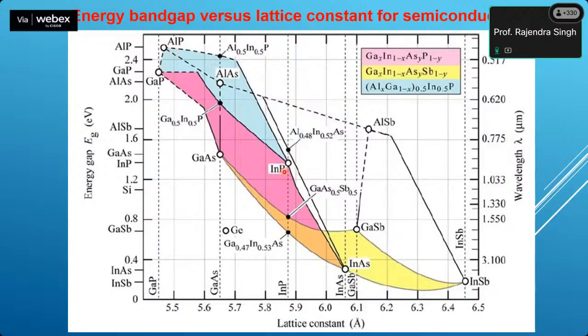But with sophisticated band gap engineering and material synthesis techniques, we can now tune the band gap. How is the tuning achieved? Tuning is achieved through alloying, or mixing. We have techniques, which I am going to talk about. We can mix gallium phosphide and indium phosphide in any proportion, from 0 mole fraction to 100%, that is, x equal to 1 to x equal to 0. So we can go from indium phosphide, through indium gallium phosphide, and ultimately to gallium phosphide.